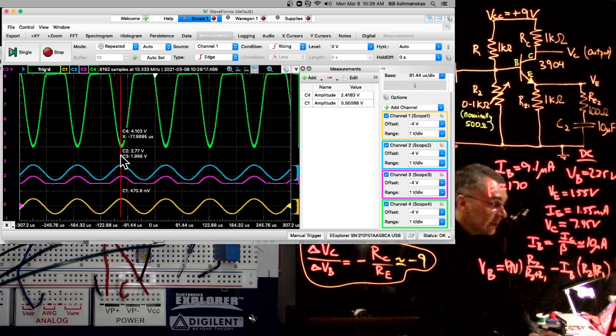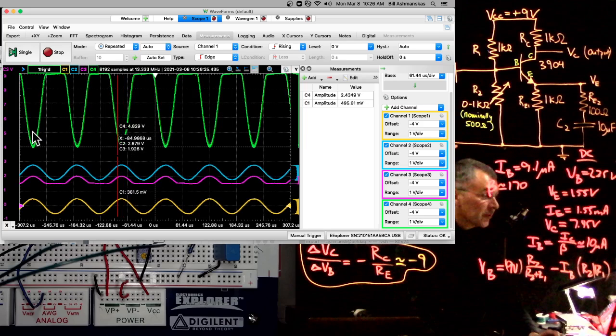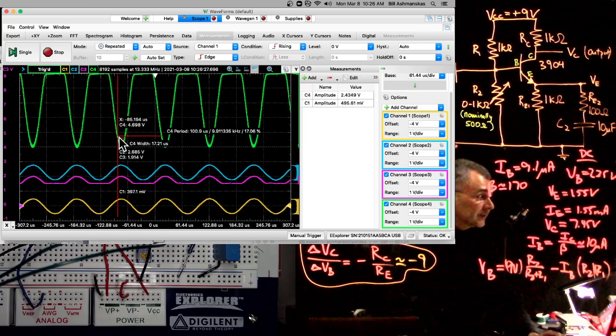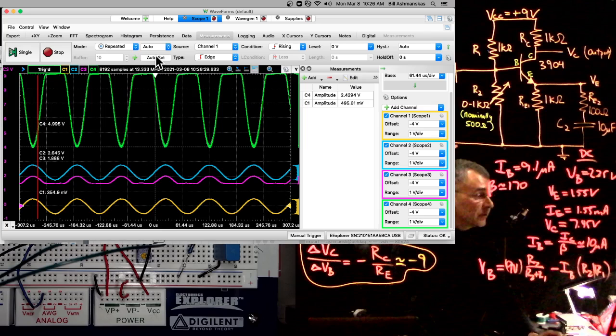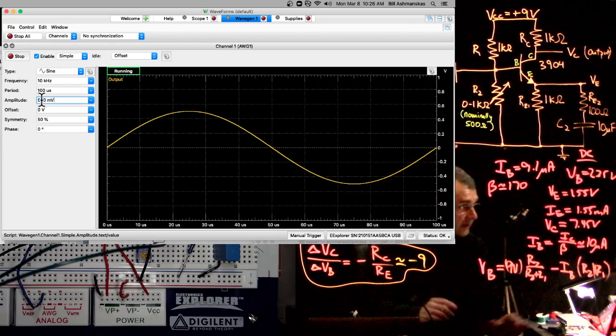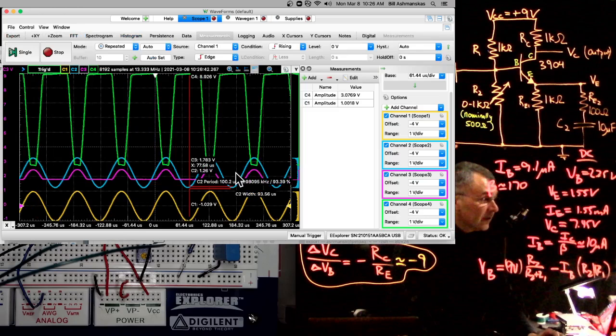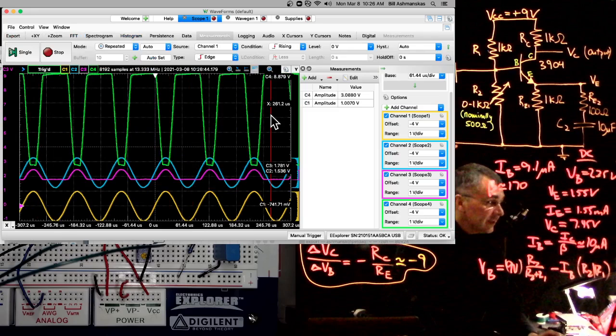We could think if we increase the amplitude even a little more, we could see this thing saturate. You can see that the bottom part of the waveform is affected by saturation. So I guess we could try to make the input waveform even a little bigger. Like how about a whole volt amplitude? Oh yeah. Okay. So now you see. And then let's change the time base so that we can, oh, where is the time scale? Oh, that's kind of weird.